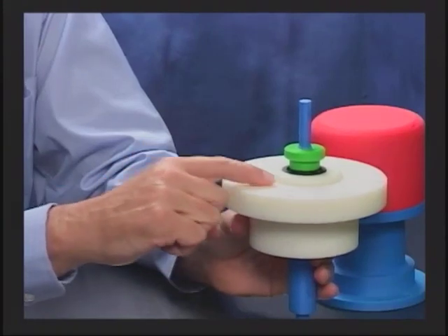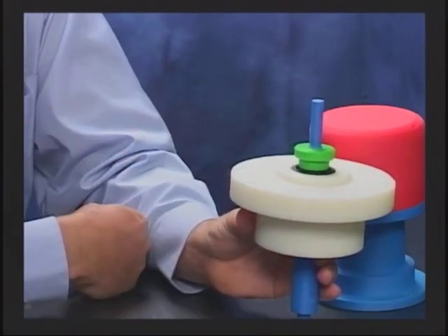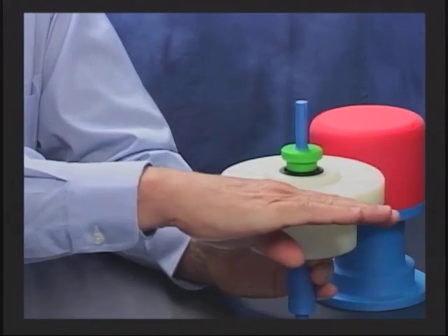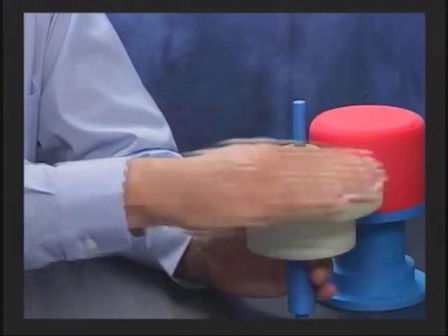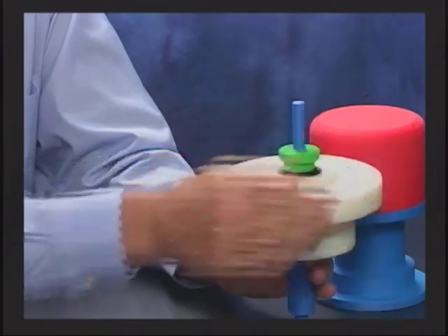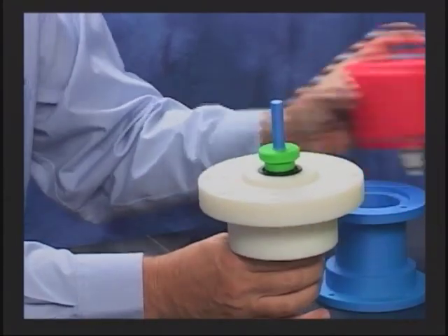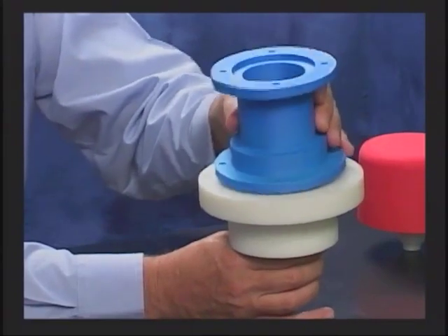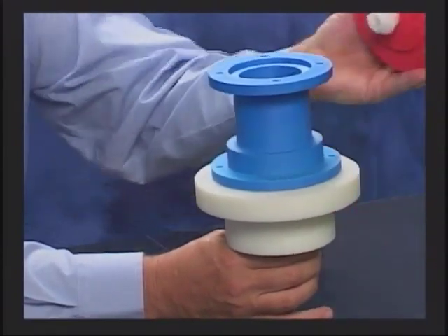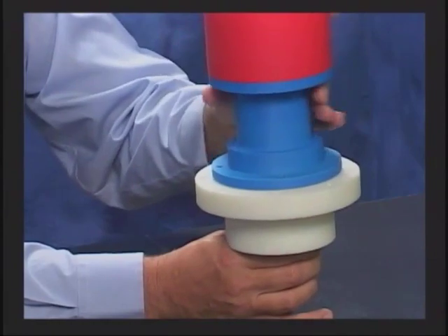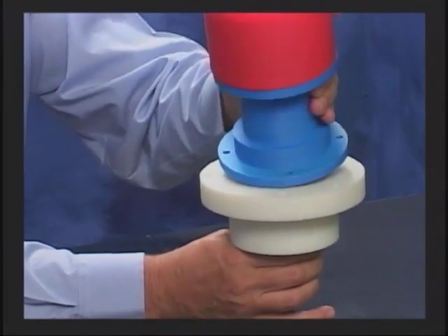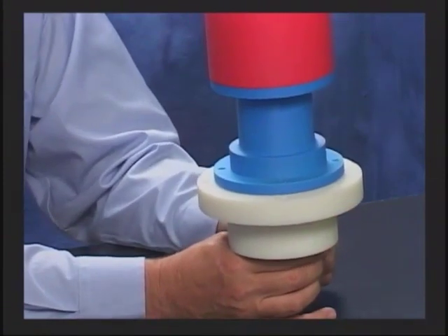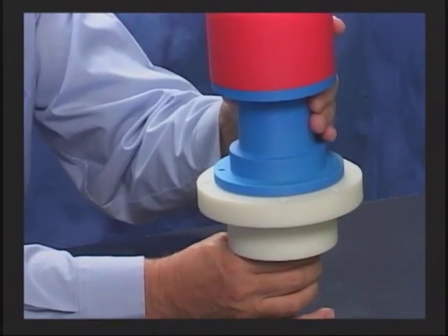And this top face over here, we gave a perpendicularity to, within 5. Now, if that surface tilts within 5, it can tilt in all different directions within 5. You know what happens when we put the adapter on top. Now the adapter tilts, and the motor is attached to the adapter, so that tilts back and forth too. As that tilts, that's going to give us some accumulation of tolerance also, and cause some misalignment.